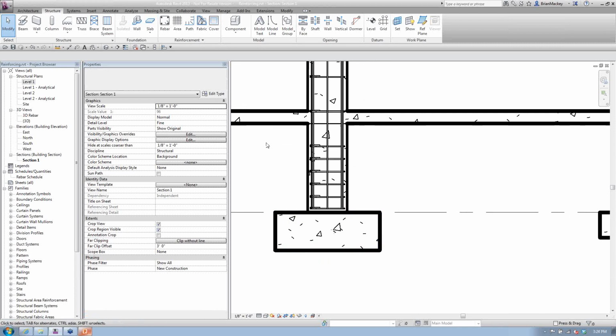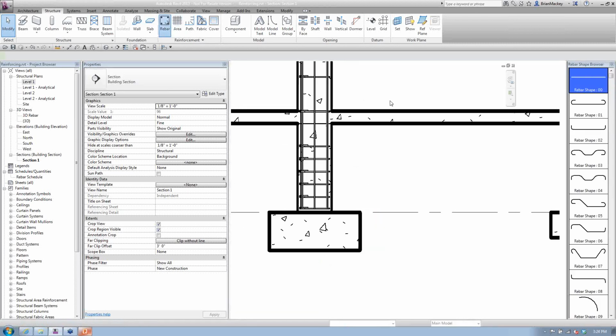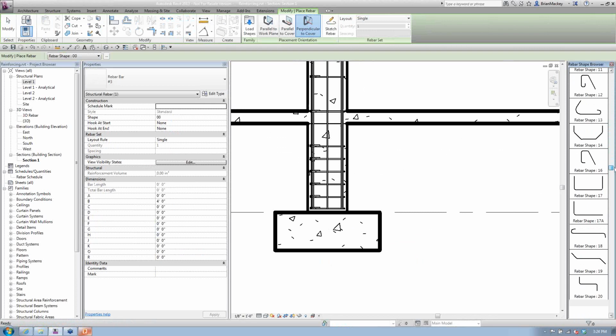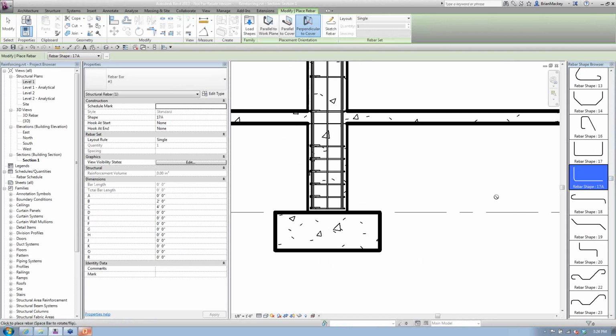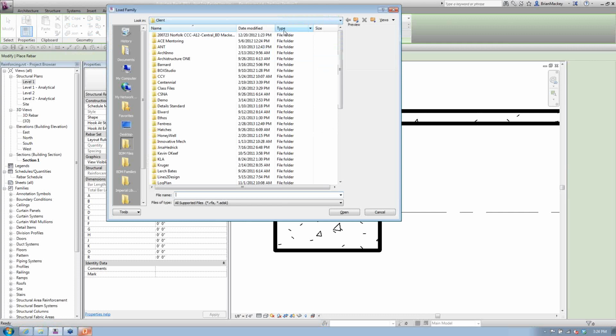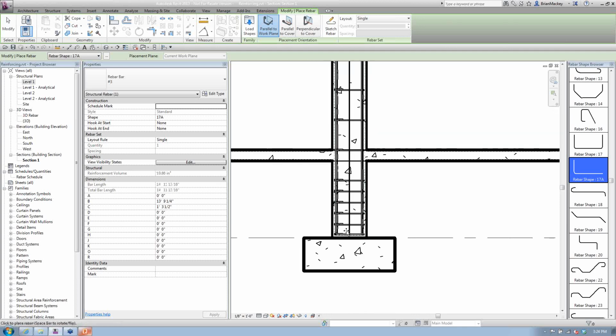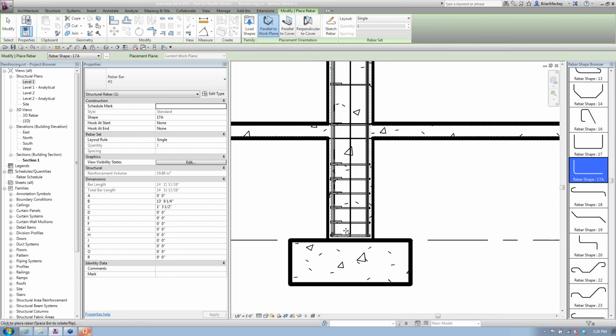The other thing is if I wanted to go place another piece of rebar inside of here, maybe I want to show a hook going from the foundation up into that. So we'll just go grab my 17A. One of the things when you start getting inside of there is the 17A isn't going to really allow me to necessarily go up into the file like I might be thinking, gee, I wanted this to go up into the family. Also, if I put it up here in the column, it's going to go the entire length.